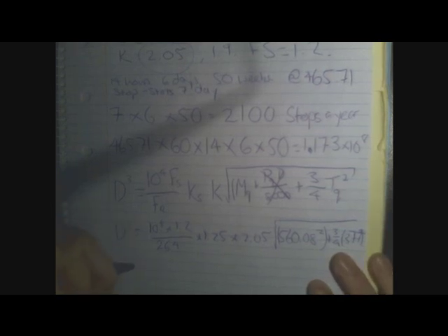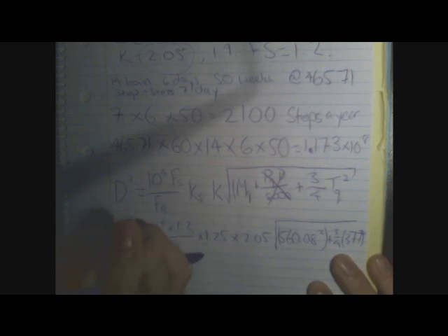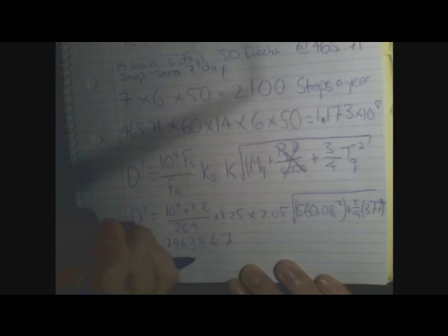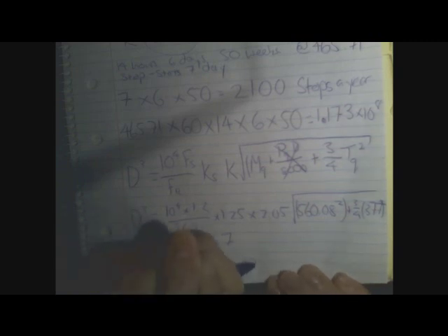That gives me a number of 78,638.67. Take the cube root of that and it will give you your diameter, which for me is 42.84 millimeters.